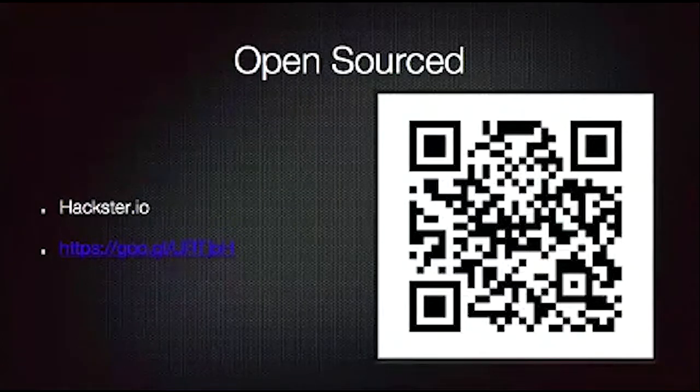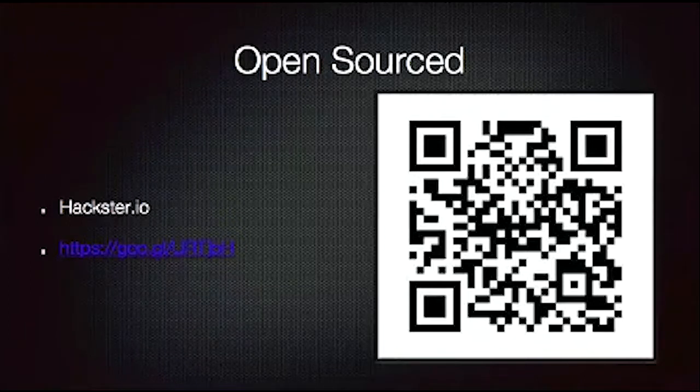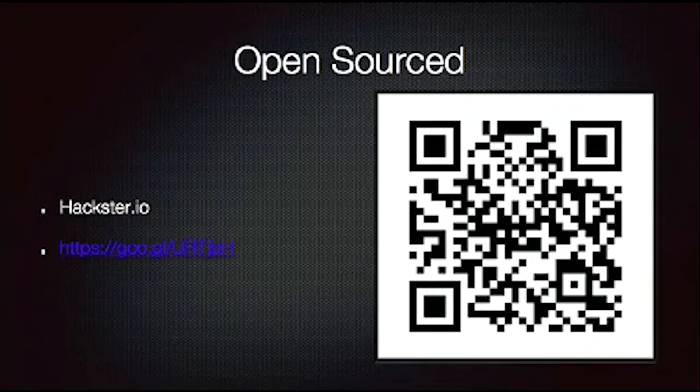It can be complicated. It can be simple. The simple part is the Arduino code is simply running through the IoT kit. What you're using is a vibration sensor, the buzzer, as well as the crystal LED display. Those are the only three things being used, running through the I2C port as well as the analog port. The RealSense sample guide will pretty much run through 90% of your code. All you really need to do is figure out how to communicate that through the USB port.